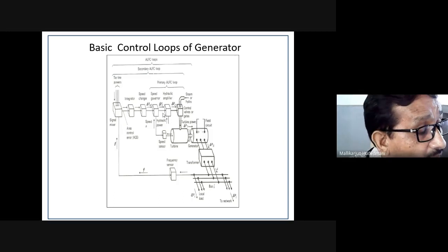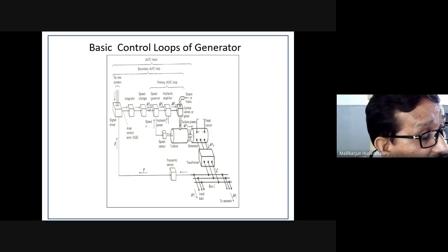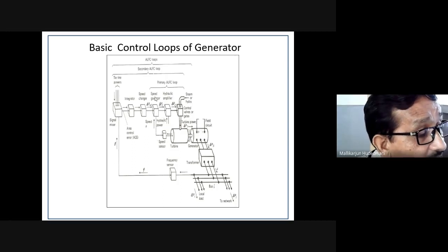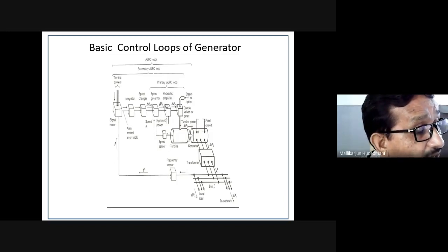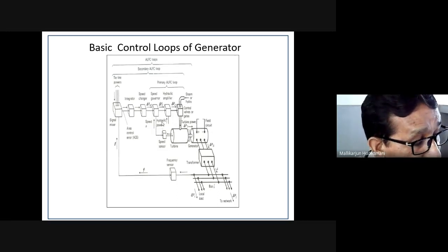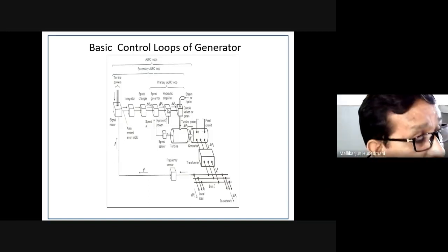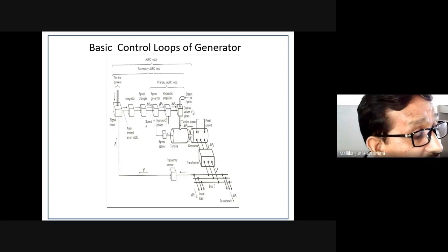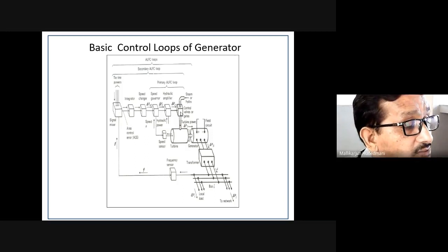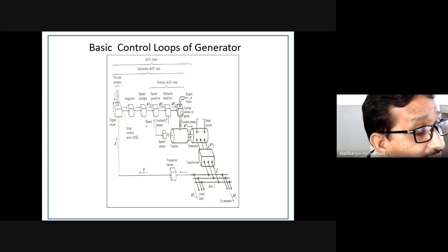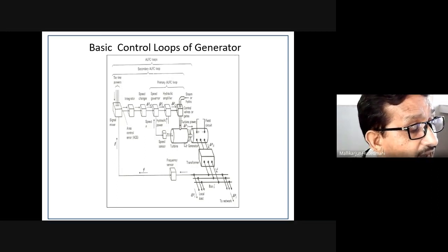On comparison of the actual RPM, the governor develops an error, a displacement error or control error, that is amplified by a hydraulic amplifier, using the flow of oil, solenoid and blocks. It will work on the control valve so that the input fuel to the turbine is managed. Once that occurs, RPM picks up.